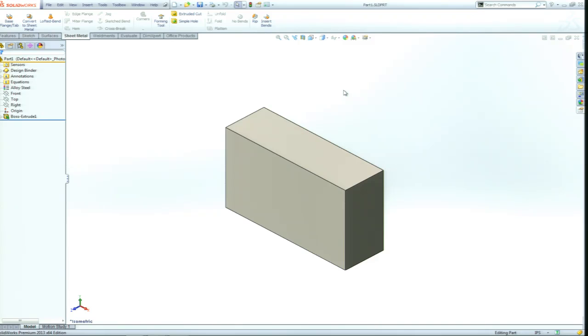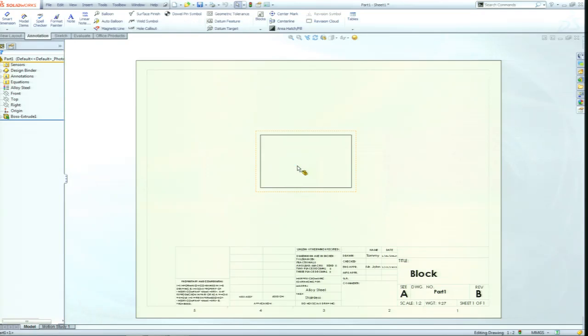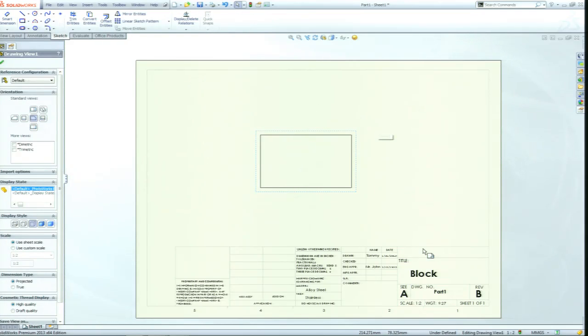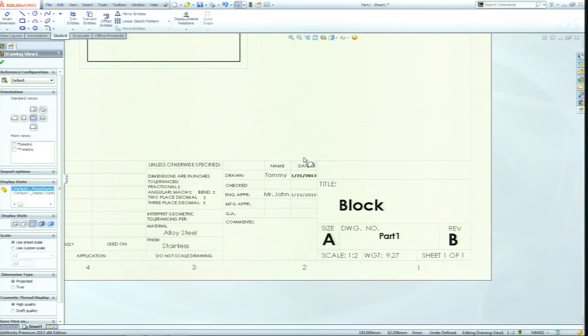There is a way to plug that in. I'm not sure if I follow exactly what you're saying. If you go to the drawing, right there it says scale ½ inch. Say that part was too big at a ½ inch, and you went over and selected a new scale for your drawing, so the part scaled down to that drawing to automatically populate with that.